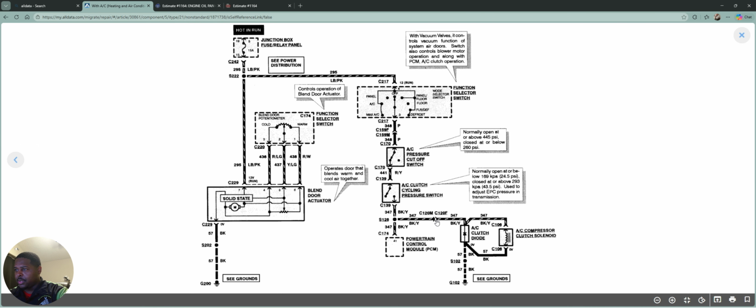Okay, so the low pressure switch harness shows 12 volts, which would be connector 139 right here. So I guess it's an electrical issue from the switch to the AC clutch, because I bought a new low pressure switch and high pressure switch. So you tested it here and got 0.014 volts. You tested it here and got 12 volts.